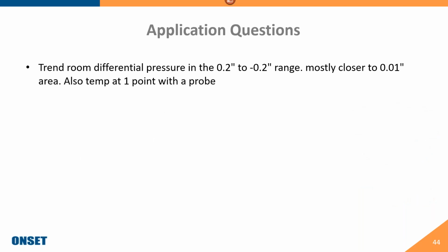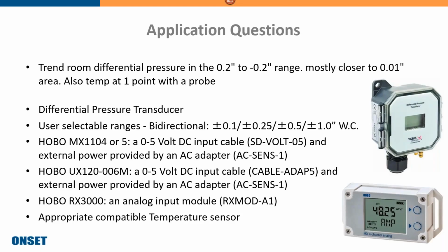And then finally, we had a lot of questions on the analog input, and this is one example of somebody who needed to do differential pressure. And I believe there was somebody early on who was looking at hooking it up to a light meter, a light sensor. So the analog input is 16-bit resolution, which we've seen gives pretty good resolution for most of those sensors that just give a 0 to 100 millivolt output. You'll see some really decent step changes, but what I would do is check out the specs there on our website.